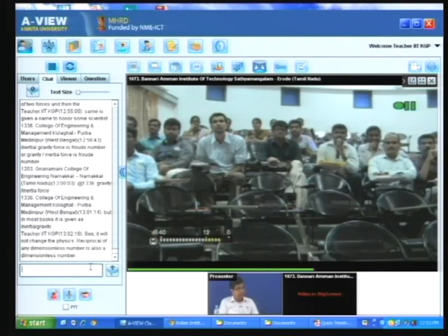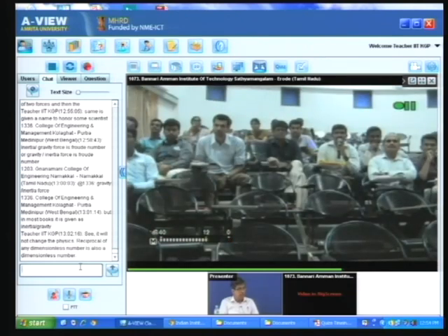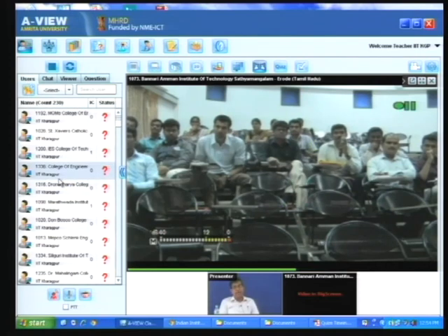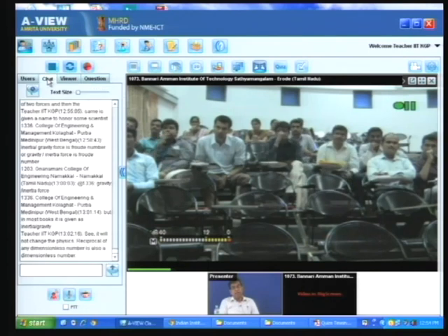Good morning. Sir, for external flow over an aerofoil, what are the model laws with regard to verification? Model laws, that is, what are the Reynolds number or Froude number? These are the things we have to make similar. Okay, yes, to make it similar, I tell you what should be the Reynolds number and Froude number range. Of course, in an aerofoil, the Froude number does not come into the picture much, it is the Reynolds number, other numbers will come, the Cauchy number.